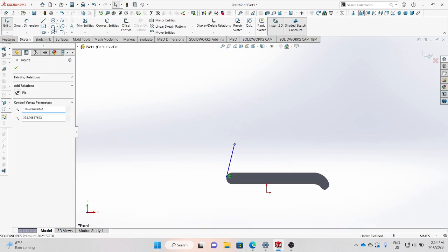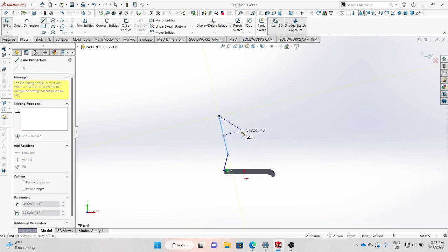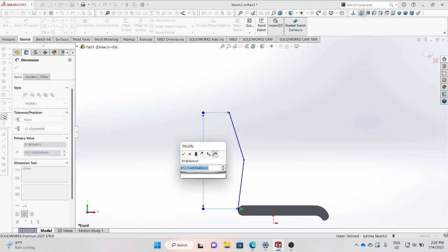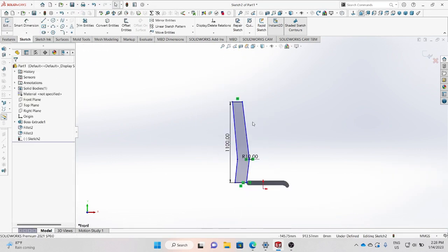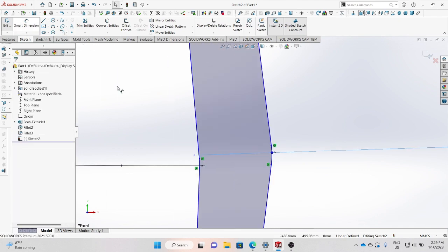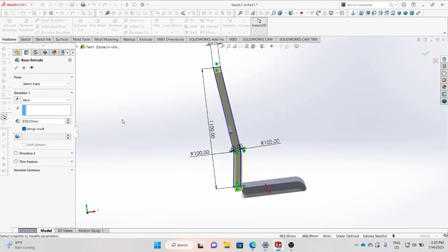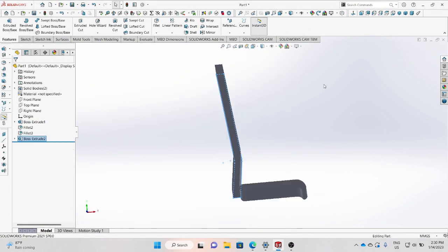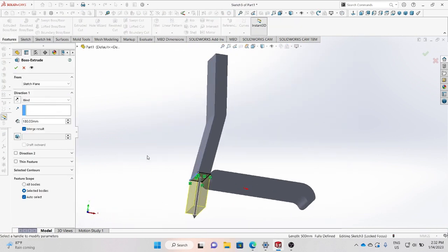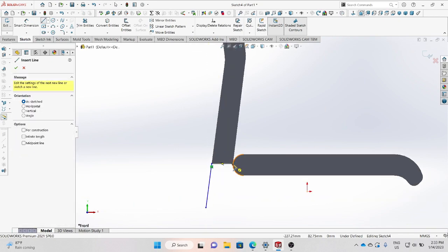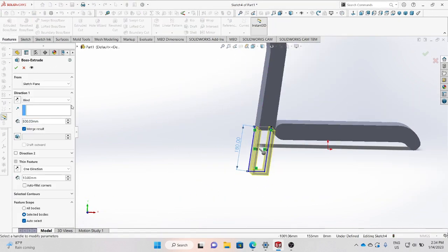So I want to talk about the drawing steps for the seat part. Okay, firstly, you can sketch on the right plane, set up a line width of 500mm and 65mm for the height. Secondly, click exit sketch and then choose extruded boss, set it to 500mm and click the tick symbol.